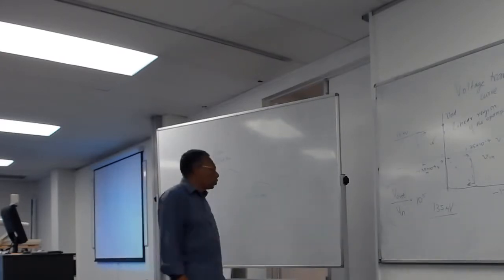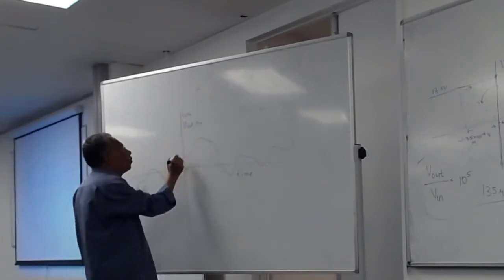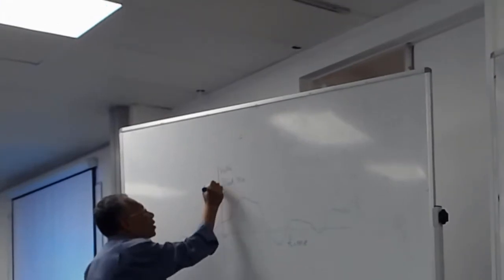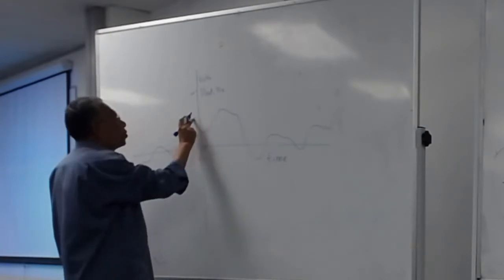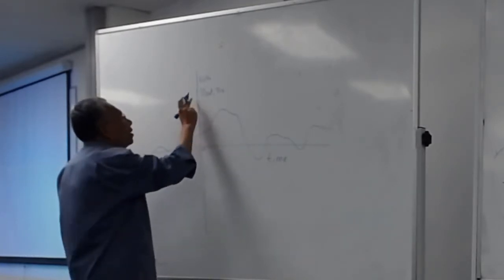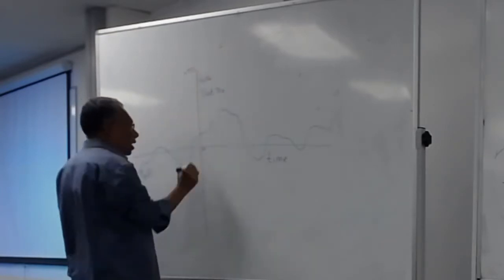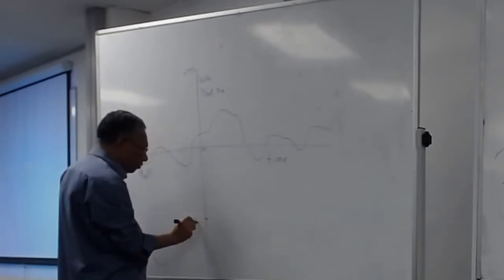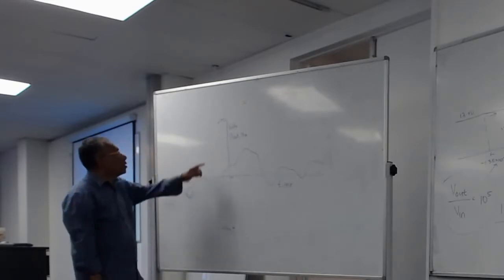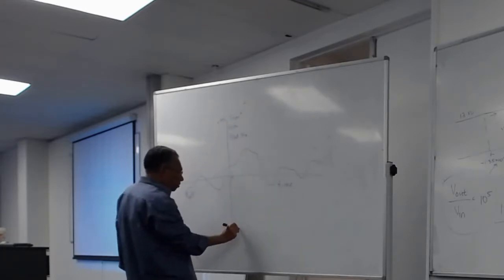So it goes above 0. This is your 0 volts. Then you can say this is your 5 volts, then this is your 10 volts. I think it's too large here, so it's not out of scale. Say you have your 13.5 volts here plus, and you scale out like this and say this is your minus 13.5 volts. So this is your Vsat plus, and this is your Vsat minus.